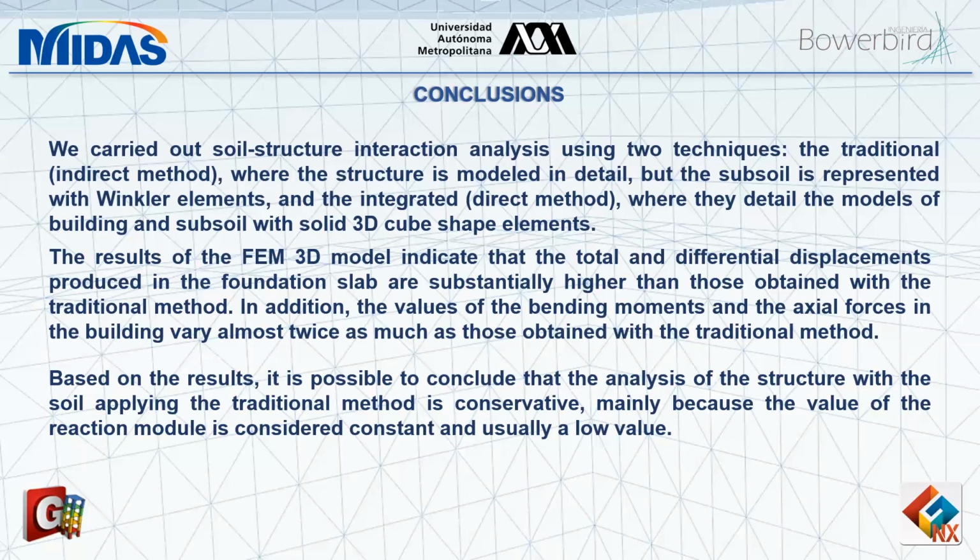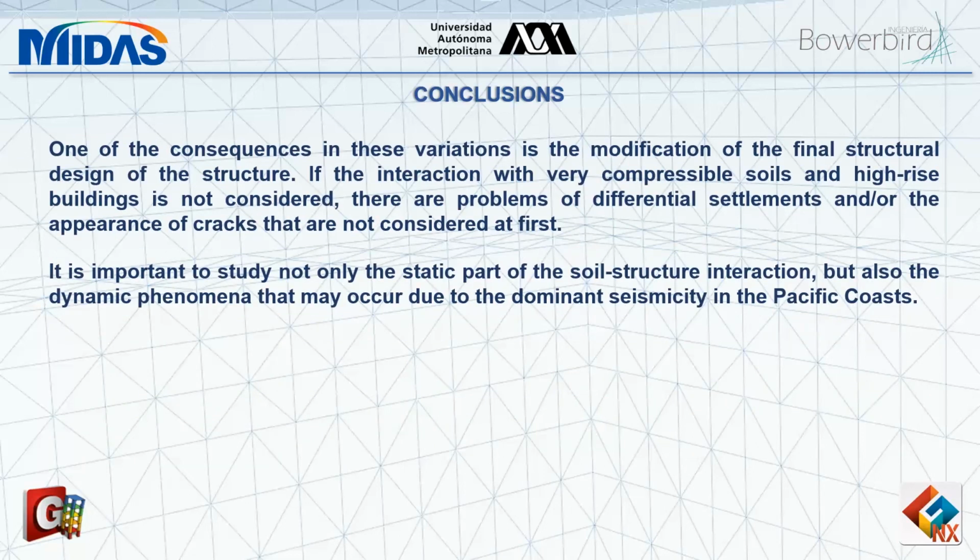So as we've seen, it's more intuitive and easier to understand how this is happening for softer soil conditions. Of course, if you were looking at a structure in stiffer ground or rock, then this wouldn't really be too much of a concern. But the issue becomes a problem when the value of the subgrade reaction modulus is going to be low, and it's hard to consider. Usually it's considered a constant value, applied throughout the piles or the raft, and you go with the lower end values just to be safe, which means you are consistently over-designing your foundations.